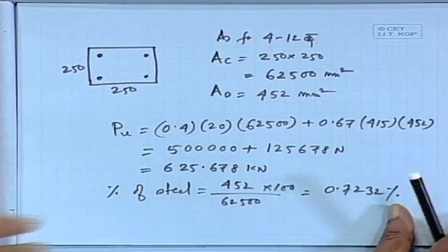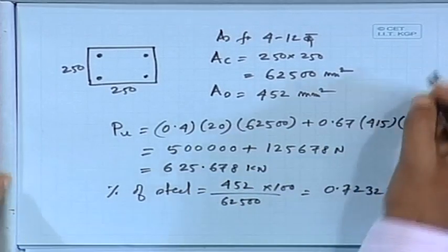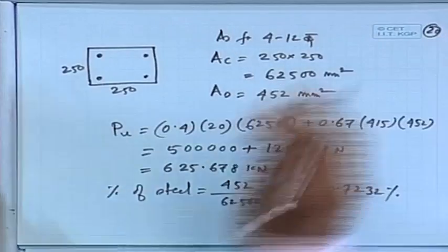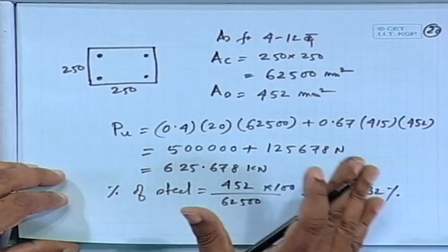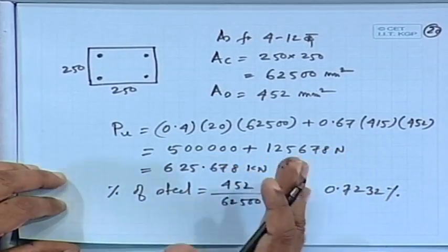It is very important, and generally we check those things. In the design of reinforced concrete, the bending moment, shear force or axial forces for an axially loaded column, you will find are very small. But even then you have to provide a certain minimum, because of cracking, shrinkage, creep, and a lot of other things, including stability. From their point of view you have to provide that minimum reinforcement.